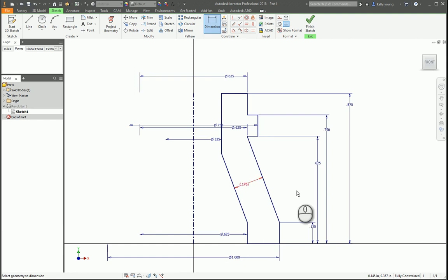Check with your instructor. They'll give you a better way of doing it. I'm guessing that from your attached screenshot, you have an extrusion, a chamfer, extrusion, chamfer, fillet, extrusion, fillet, sketch, hole. So you're pretty much doing 10 commands where one command works. So simple is better and gives you more control, especially on revolved parts.